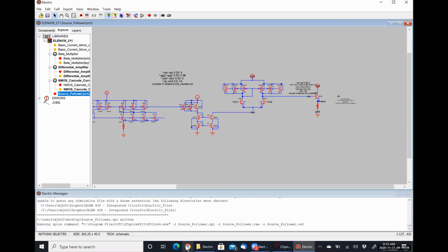And that seems to be working right. Like I said, if I do it really slow in my hands, it'll turn the servos the right way, and it works fine. And if I take the servos off, it works fine. But as soon as I plug the servos in and it goes from forward to backwards, it pulls the Arduino off for like a second, and then it turns back on. But that's too long. And then I'm tuning it with a potentiometer.